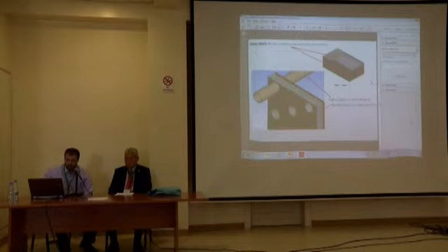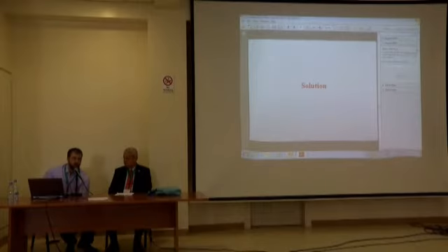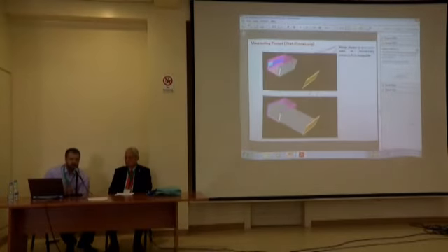The other walls of the unit are modeled with no-slip conditions. That is, the velocity is zero at the walls, and they are insulated. And remember, between the two fluids we have the solid region, which is made of fins and pipes. In this case, the pipes are made of copper and the fins of aluminium. So now, once we have identified all these inputs, we run our solution. We hope it will converge. And then we post-process our results.